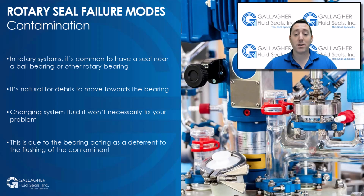Next, we are going to talk about the second failure mode of rotary seals, contamination. In rotary systems, it's common to have a seal near a ball bearing or other rotary bearing. It's natural for various debris in the system to move towards the bearing. This causes further debris to loosen and part from the bearing, ultimately damaging the seal. You might think that changing system fluid would help with the issue, but changing it won't necessarily fix your problem. This is due to the bearing acting as a deterrent to the flushing of the contaminant. This actually tends to lay near the seal.